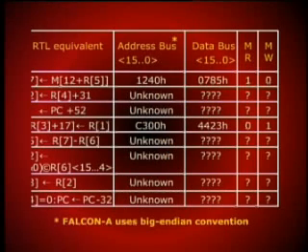For this load instruction, the address should be the contents of register R5, which from the previous table you could see is 1234 hex. To this we need to add 12. 12 is in decimal, which is equivalent to C in hex. So when we add 1234 plus C, that turns out to be 1240 in hex. So therefore, on the 16 lines indicated by address bus, the data or the number available would be 1240 hex.